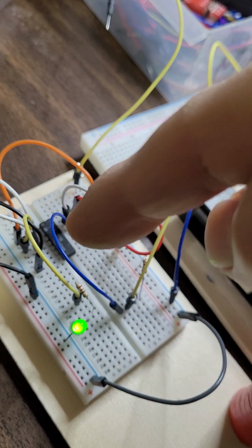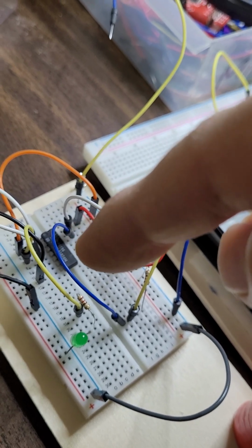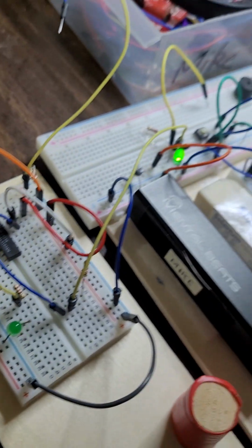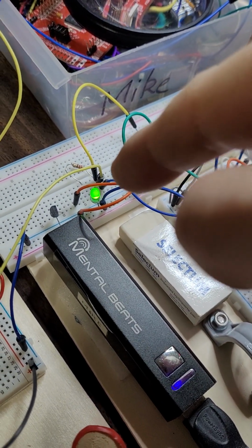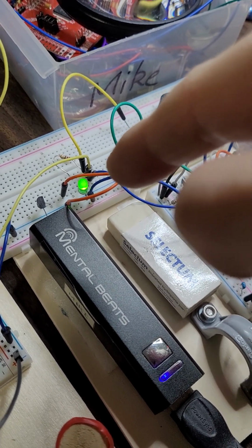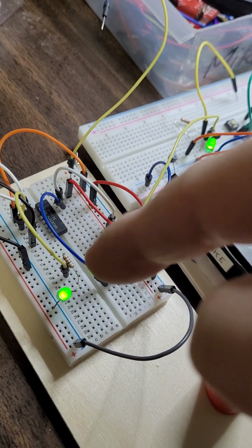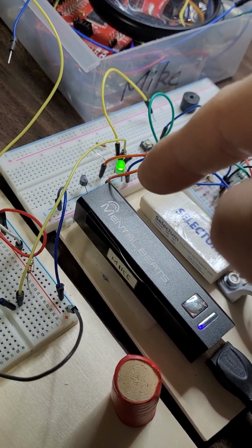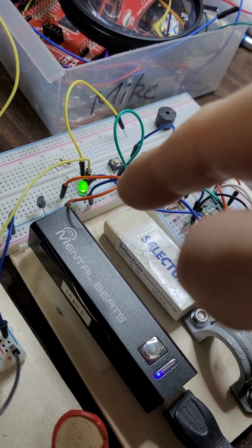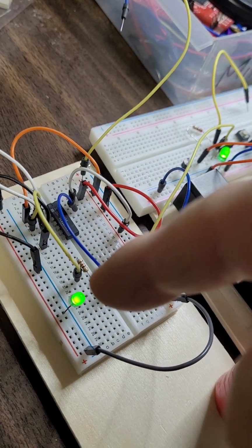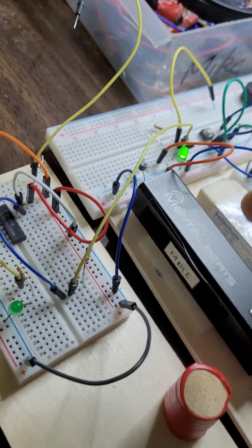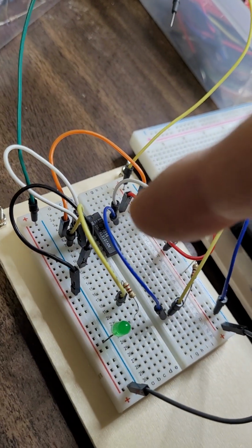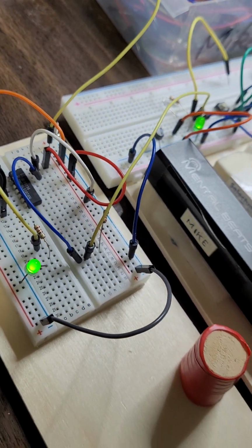You see that the JK flip-flop is now providing a square wave of 1000 milliseconds, or 1 second. So a square wave with a cycle period of half a second now gives us a square wave with a cycle period of 1 second, because we are passing the half-second output to the input of the JK flip-flop. And that's what a JK flip-flop does.